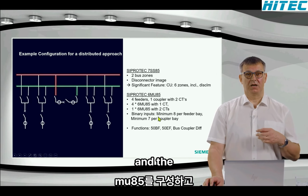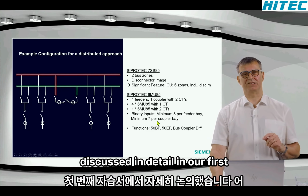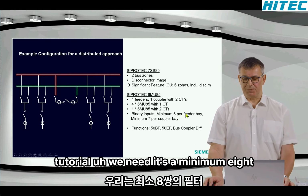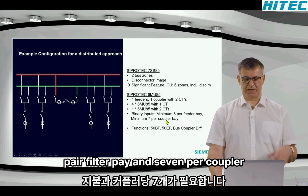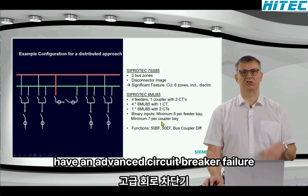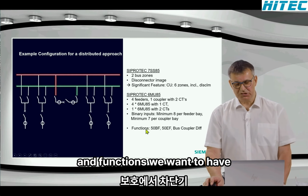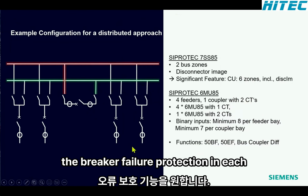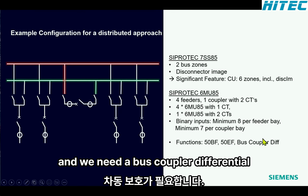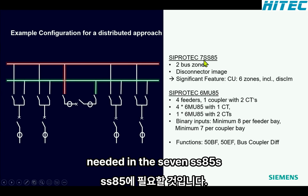And the requirements according the binary inputs, binary outputs, LEDs, we have also discussed in detail in our first tutorial. We need in the minimum 8 per feeder bay and 7 per coupler bay, because in the coupler bay we will not have an advanced circuit breaker failure protection and circuit breaker failure protection, which could be started from an external device. And functions, we want to have the breaker failure protection in each bay unit, and end-fault protection, and we need a bus coupler differential protection. This bus coupler differential protection will be needed in the 7SS85.